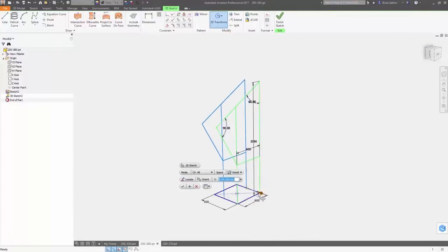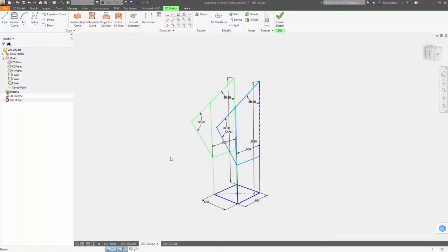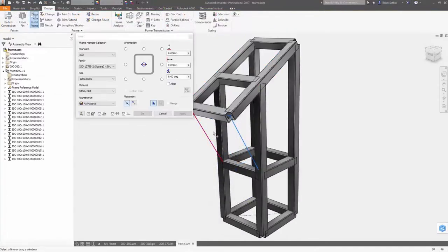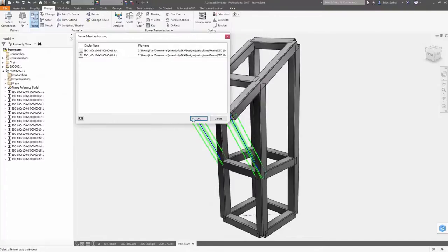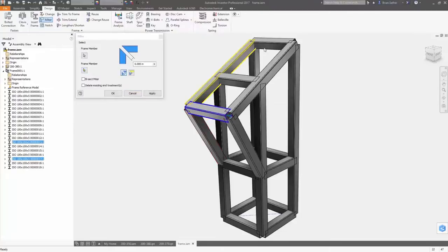Reusing 3D sketch geometry is now easier with the ability to copy and paste inside the original sketch or between 3D sketches. Once the copy is created, the new 3D transform command makes it easy to move and rotate the object to right where you need it. With Inventor 2017, you have more control and a set of intuitive tools for creating 3D sketch geometry exactly the way you want.